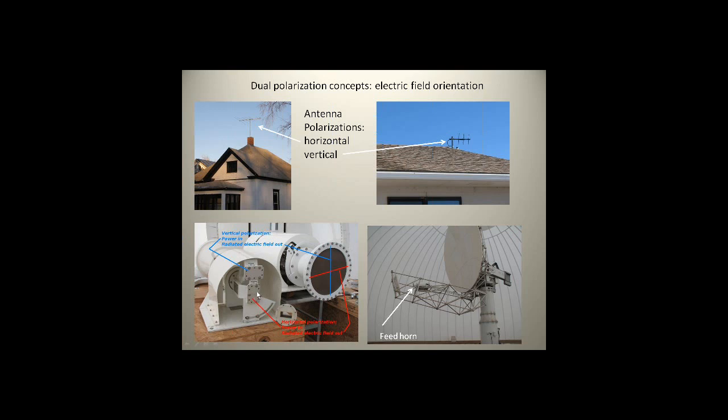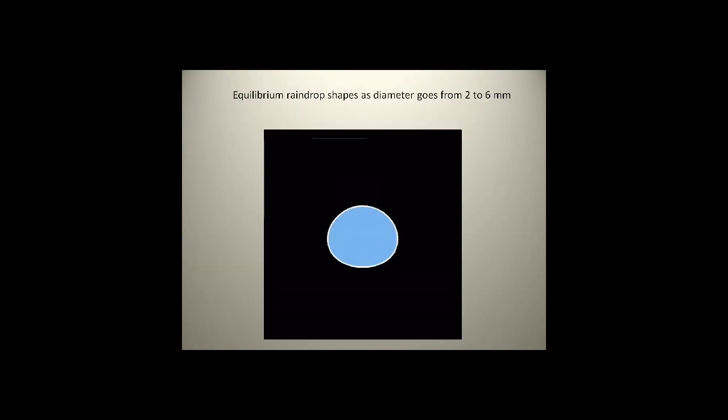And in this case, if I put microwave power into this port here on the bottom of this particular feed horn, that means what comes out the front end will have the electric field vibrating in the horizontal plane. And similarly, if I energize this port, my pulse is going to go out with the electric field vibrations in the vertical plane. Now the same thing happens on reception. The signal that gets backscattered to the antenna lands on this reflector. It goes to the subreflector in the case of our antenna, and then it re-enters the horn going towards the radar receiver. And that signal that lands on the face of the horn will be separated into horizontal and vertical components by this feed horn. So with a dual polarization feed, we can control the polarization we're sending, and we also separate out the polarization components of the signal that comes back.